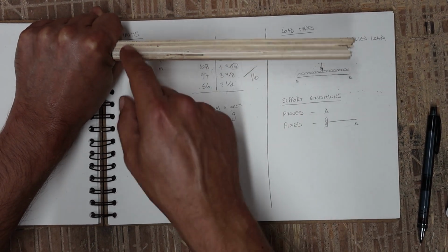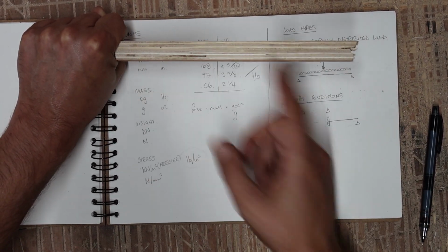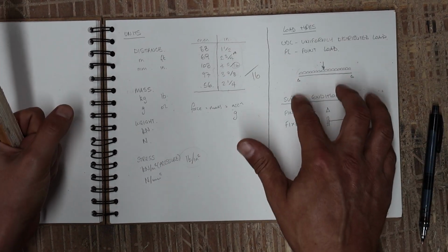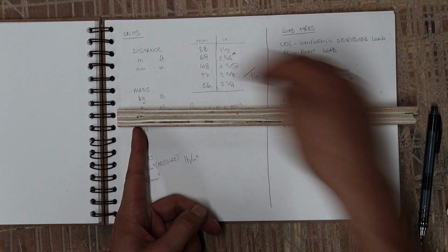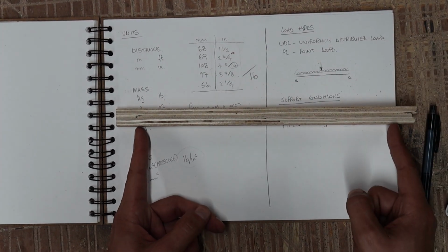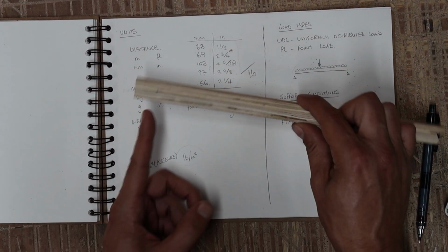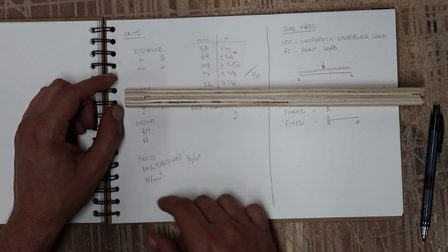So because we've got a fixed support condition, the beam deforms differently as a result of having a fixed support, whereas what we'd normally do for beams is just assume pin supports at both ends. So any force that's exerted on this beam just gets transferred to one of these supports, and the beam is technically free to rotate at the supports. That's all in the maths.